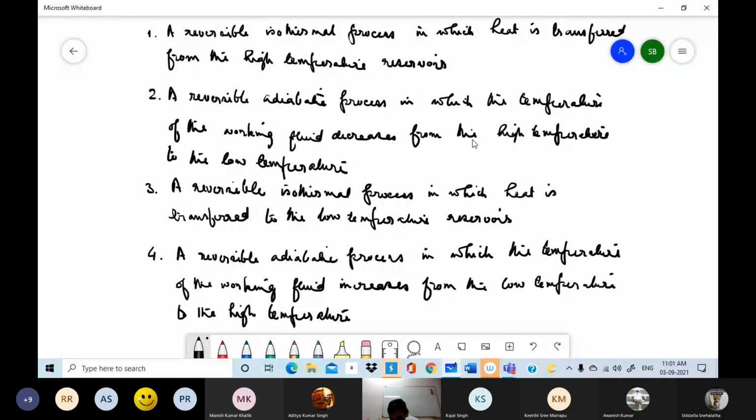If you look up books, there is such a diagram given for the Carnot cycle, but the adiabatic process is a straight line if one of the coordinates is entropy. And the problem is we have still not defined entropy, so we are still not in a position to draw this. But at least we know what the definition is: two isothermal processes and two adiabatic processes.